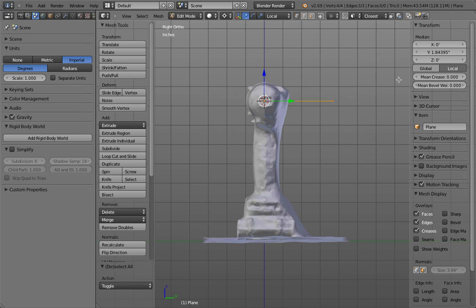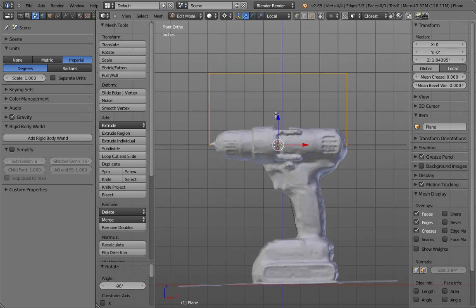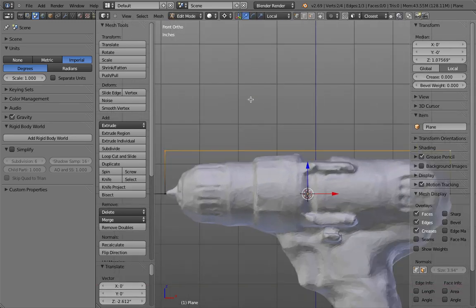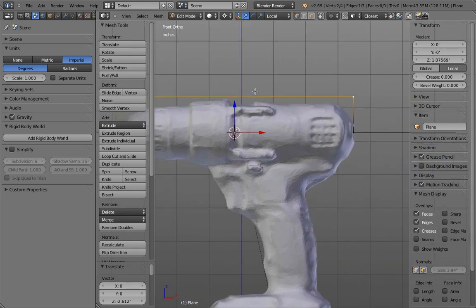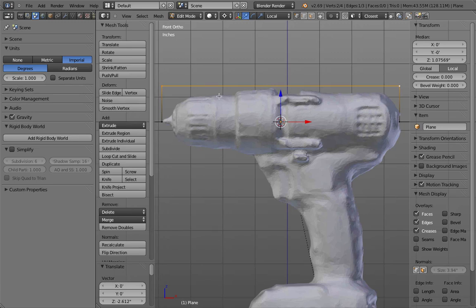And then from a side view, for example, I can press R, and I have to type in -90 degrees. So you see, like, I framed it, and then those points I can move slightly down. And the whole point for this is simply I can now use this to start building in different features. So to subdivide, for example, this line, you can select an edge, go to mesh tools, and then where's subdivide, there. And then it will add a point.